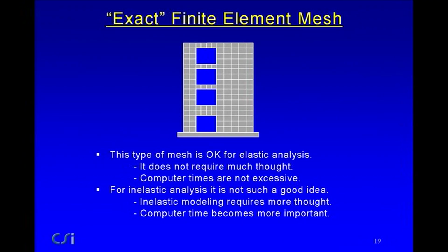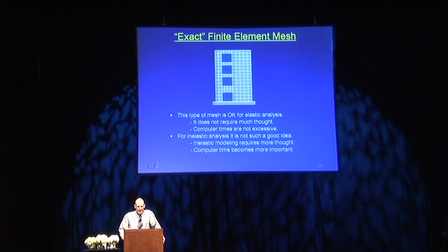A nonlinear dynamic analysis involves 1,000 or 2,000 or maybe even more time steps. And so the computer time is going to be of the order of 1,000 times larger than it might be for a single static analysis. Much, much larger. So you need to start thinking about whether your mesh is overkill or not.